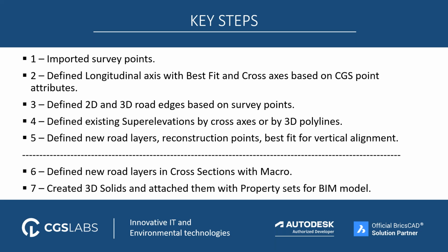Then we created road edges semi-automatically by connecting points with the same attribute. Then existing superelevations were defined by cross-axis or with 3D polylines. And then in the last step, we defined new road layers, drew the reconstruction points, and used the best fit for vertical alignment.